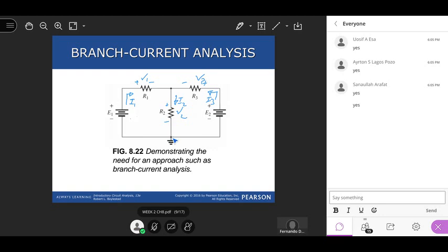For me, I think it's more intuitive for inexperienced students to learn it this way: from low to high, positive, because it's a voltage rise, and a voltage drop is negative. So intuitively you can remember to use it through the whole circuit. But you can use whatever you want as long as you use the same concept through the whole circuit.